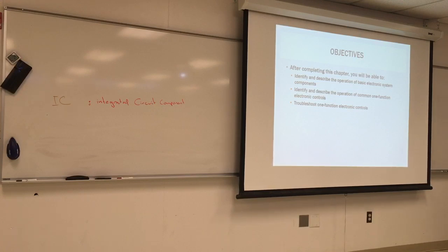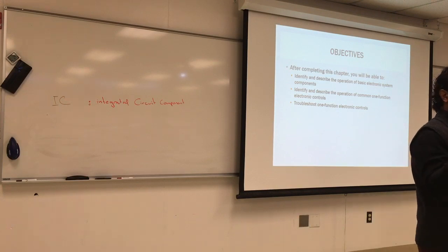So these actually get sent out, and they have somebody who will go and troubleshoot them. It's very involved, and probably they have a schematic where everything goes, what the resistance is. So they will do something like you would do with the big board, but on a small scale. They'll test the voltage for each one of those, test the resistance, and find which integrated circuit is not functioning.